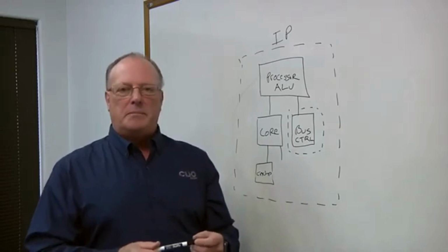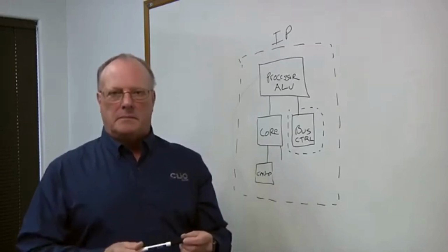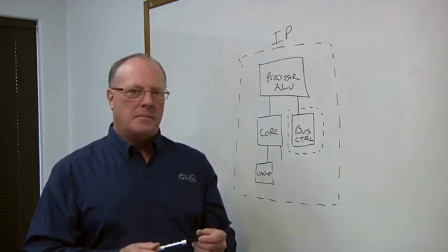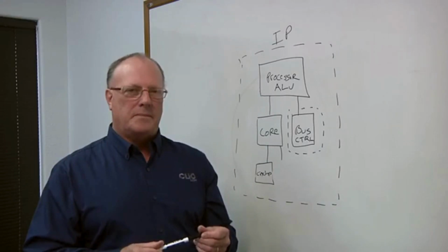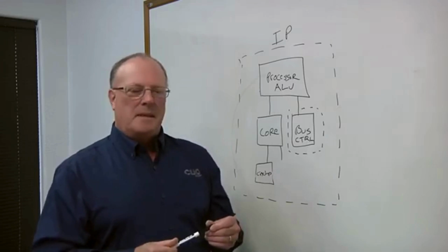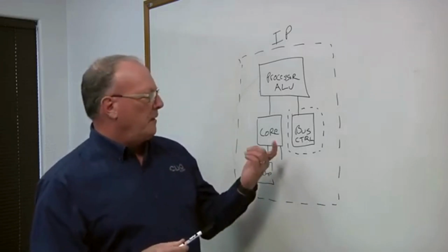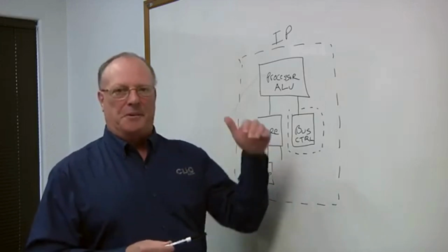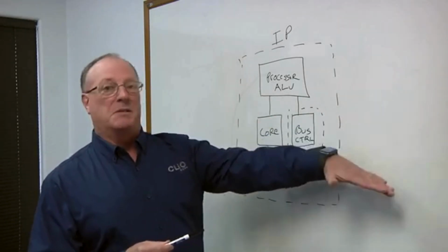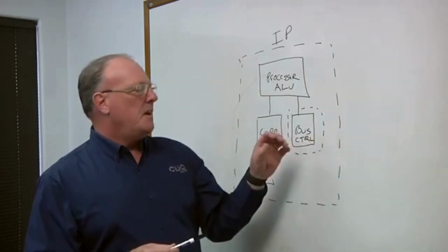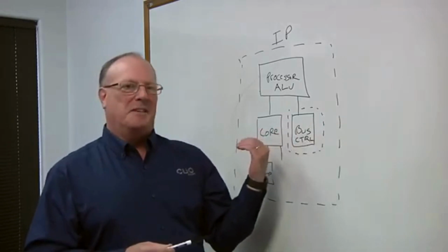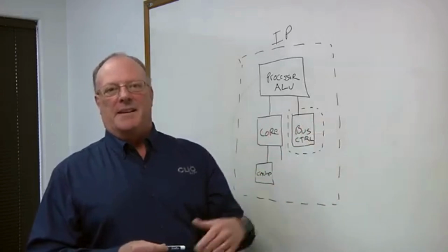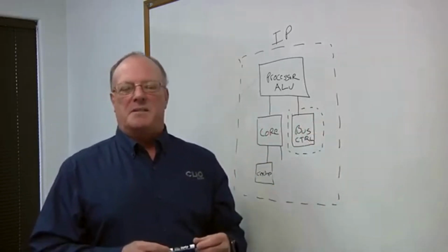One of the issues that comes up with IP is security as well, particularly in terms of not so much what's in there, but what you don't want to be in there. So, what can it do and what shouldn't it do? So if you have something like an ITAR block that shouldn't be shipped to a particular area, and so you make something specific for a particular geographic region, you can look for the presence of these secure IPs within your tape out and say, whoa, that shouldn't be there. And you can stop it before you actually make masks.